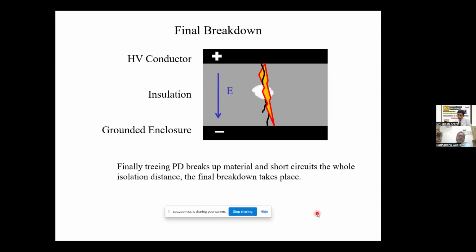Specifically, the insulation defects are not reversible. They are irreversible. While testing equipment, you may find that the partial discharge was active, especially in a GIS. If you have a free particle, it was active, but you just switch off that portion of the GIS and switch on.